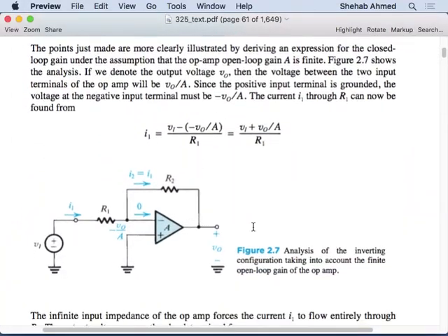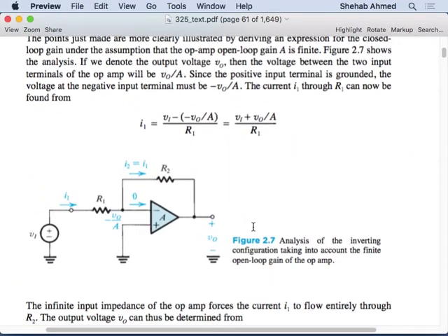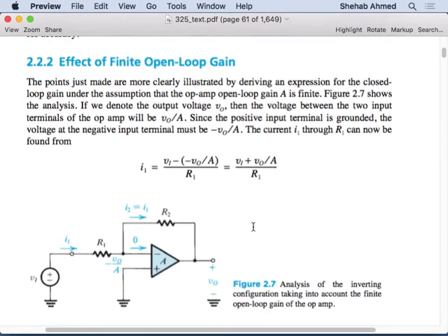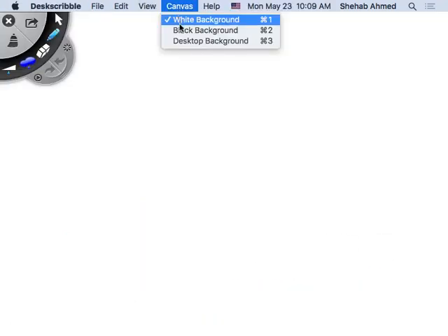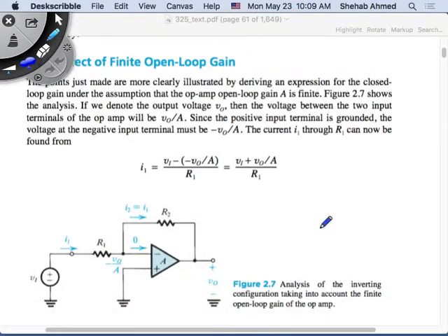Now the nice thing is, we developed an interesting story around the idea of utilizing the op-amp open loop gain as being infinite, right? This idea of the open loop gain being infinite brought us certain interesting and simplified things, and gave us control over the gain of a circuit that we would like to develop.